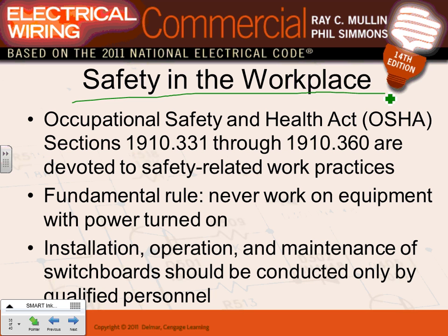So when you work on energized equipment, guys, the rule is: lock it, tag it. Only qualified people are working on it, right? And then you work on it. If you are to work energized, there is a work permit that you have to fill out. Almost six people have to sign that work permit, all the managers, to make sure that you exhausted every option of working on this piece of equipment de-energized before you start working on it energized. And then you put on your personal protective gear rated based on arc flash, and then you start working on it. So all these are requirements so you don't kill electricians.